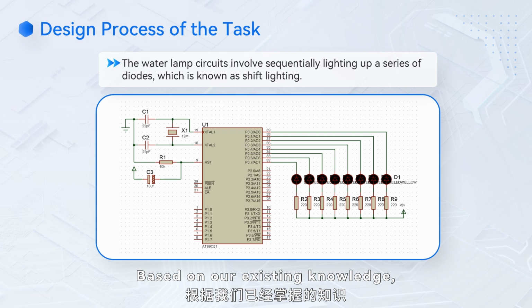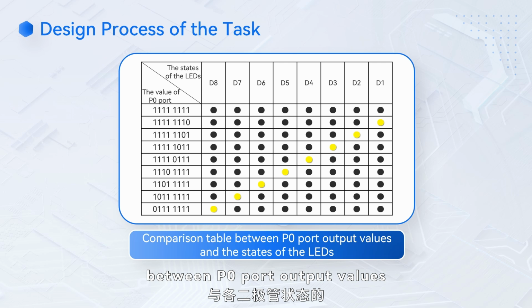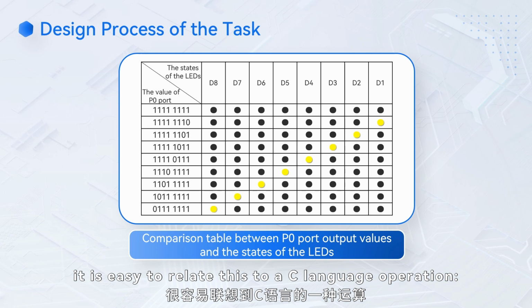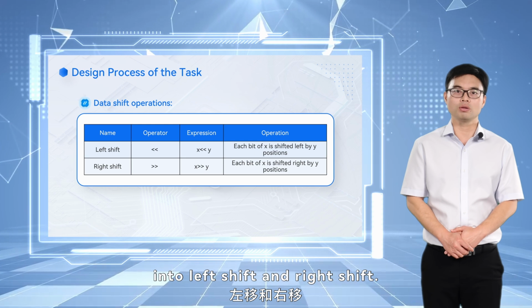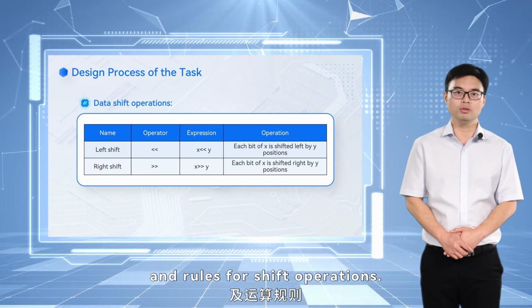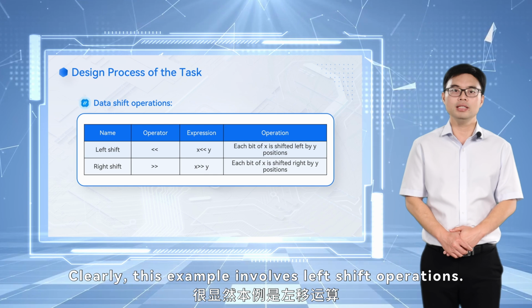Based on our existing knowledge, we have listed the correspondence between P0 port output values and the states of the LEDs. Observing the changing patterns of the P0 port output values, it is easy to relate this to a C language operation: shift operations. Shift operations are divided into left shift and right shift. The table shows the syntax and rules for shift operations. Clearly, this example involves left shift operations.